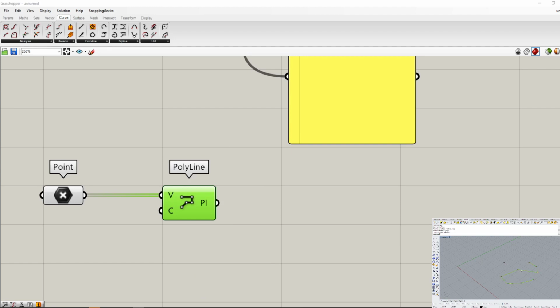And if I click where that polyline is, I make a copy of it, right? I bake it into the Rhino file. If I try and select it at the moment, there's nothing to select because it's not there. It's only in Grasshopper. So if I move a point, it automatically updates. Let me just close my C-planes option. Sorry about that. It just moves a point around pretty obviously. But what's really cool is it doesn't leave behind a copy.